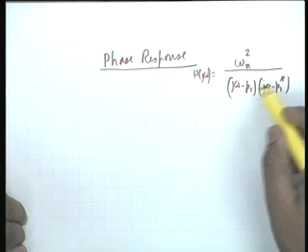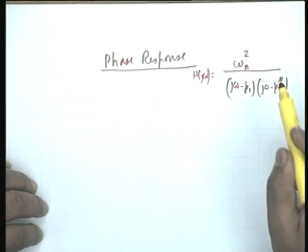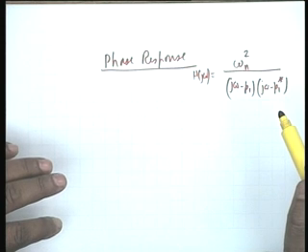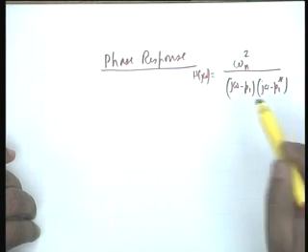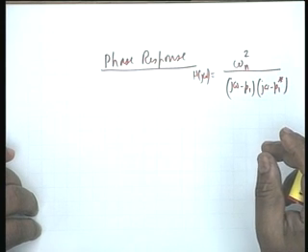I can of course substitute P1 and P1 star and do it analytically. I can find an expression for the phase response. But if you go from the mathematical expression, the chances of making a mistake are much greater in the case of phase response than in magnitude response, because in the phase response there are ambiguities. 0 and 2 pi cannot be distinguished from the tangent of the function.